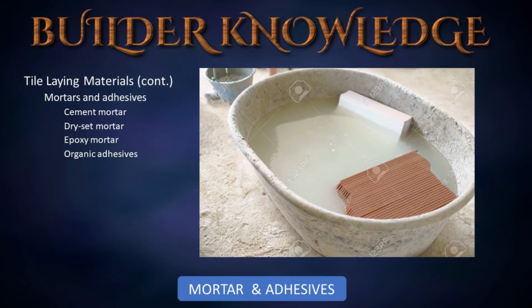Tiles require soaking in water for a minimum of 30 minutes prior to installation, using cement mortar. A waterproof backing is sometimes required, and the mortar must be damp cured. Cement mortar provides a bond strength of 100 to 200 pounds per square inch.